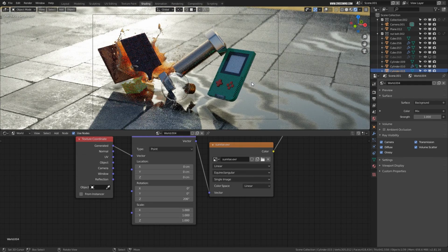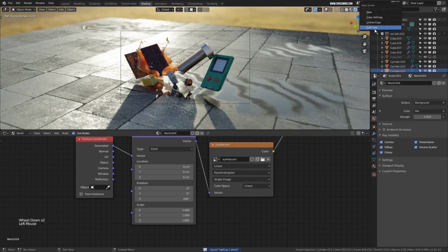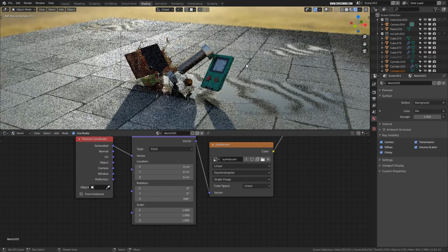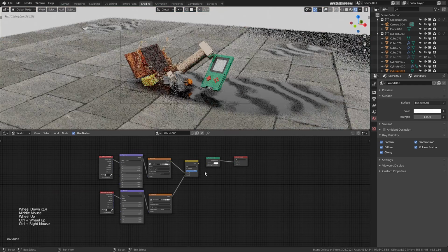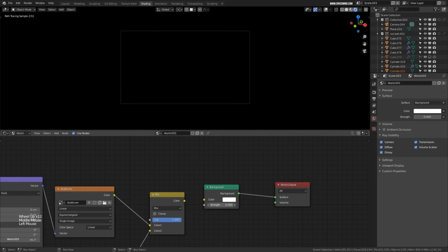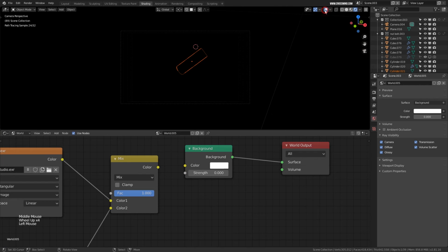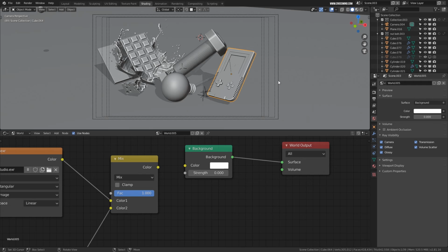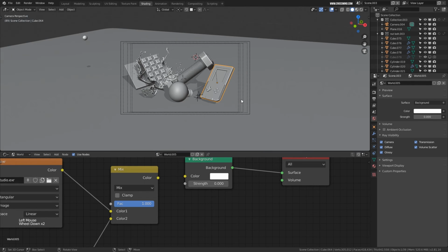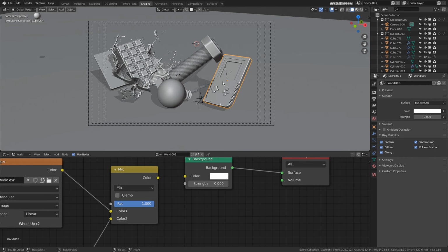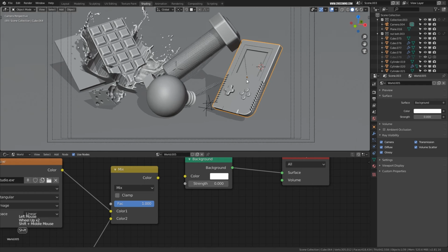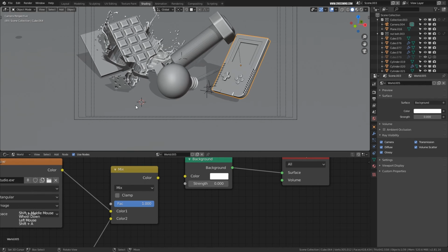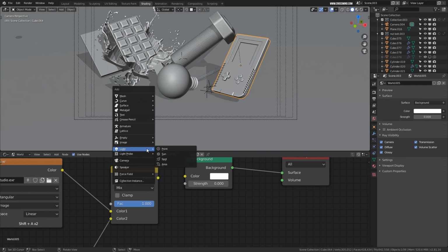which are lamp objects. So I'll just make a copy of this scene for the sake of backup, and I'll remove these nodes in the background and turn the intensity down to 0. So now our scene is back to black. Now the second category is the lamp objects. Just like real world artificial lights, almost all 3D packages have these artificial lamps. You can bring these by pressing Shift A, and in the Light category over here you can see there are 4 different lamps.